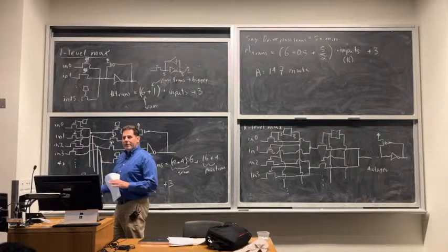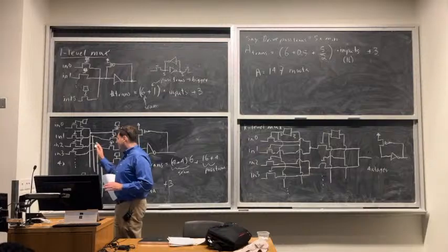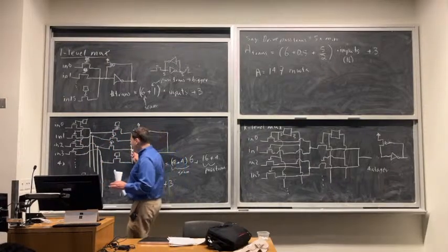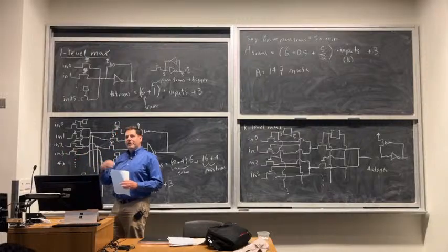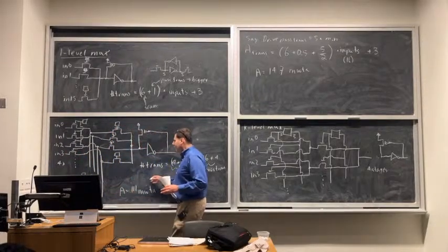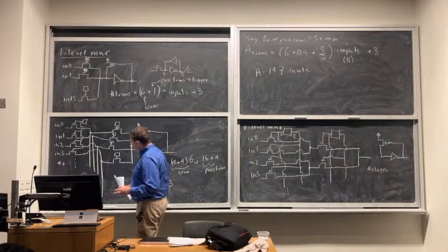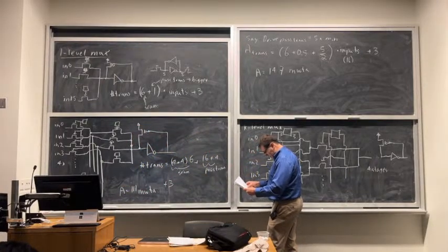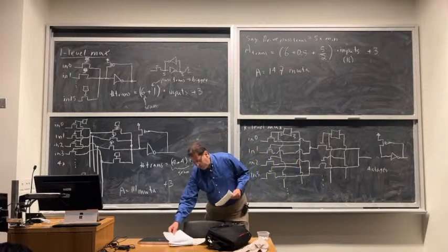So the speed of this is a little slower than single level, but not too much. It's because it's 2 pass gates discharging this capacitance instead of 1 in series. So it is a little slower, but it's significantly faster than the K level one. So it's a pretty good trade-off. Yeah, so that basically is where that one stands. So it's the smallest. It's also pretty fast.